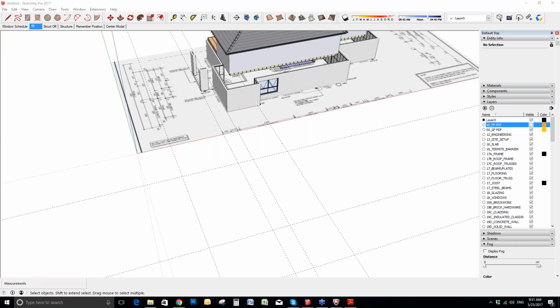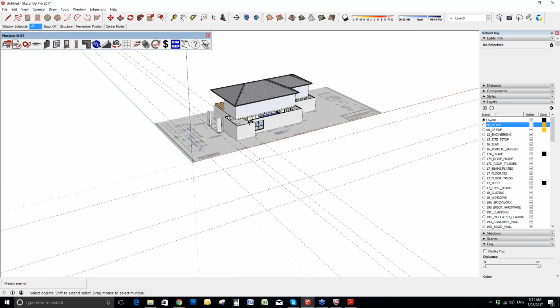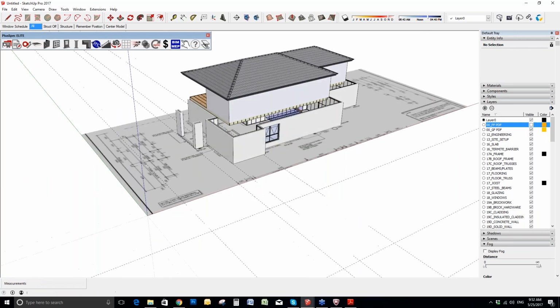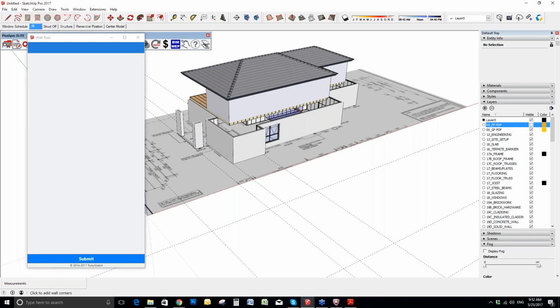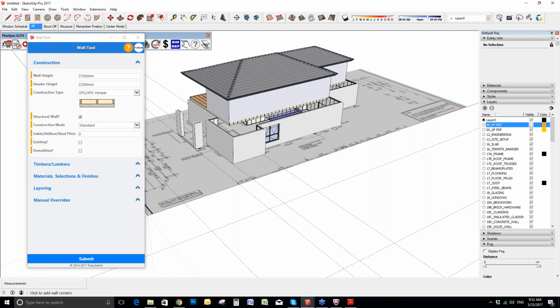Can you use a material to represent an item and have it quantified? We're going to be going into that in more detail in part 2, which is our advanced takeoff and estimating. You can. Any material that you create with PlusSpec, our materials are intelligent. Not only are they BIM, which means they're filled with information, but they're also tied into the ability to quantify. As long as you're using a PlusSpec material, and you can use the PlusSpec material creator to do it, then they will be quantified. In all of our tools, you'll see that every single material has a different layer, has a different item.